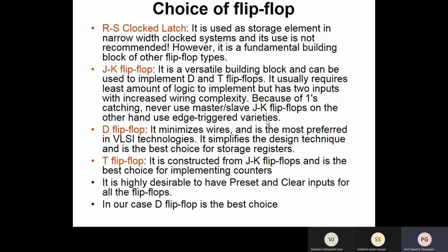Then T flip-flop, which is also called as a toggle flip-flop, it is constructed from the basic JK flip-flop and is best for the implementation of counters. Okay, so again, at the same time, it is also desirable to have the preset and the clear inputs for all the flip-flops. So in our case, D flip-flop is the best choice because it is simple.